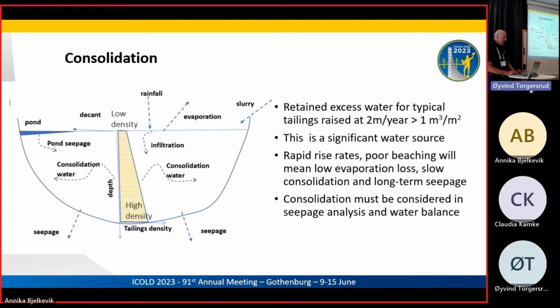And if we have a rapid rise rate, if you're putting the tailings in even more quickly than 2 metres a year, well, then we're going to end up with a lot of water trapped. And the more water that's trapped, the more is going to contribute to seepage.